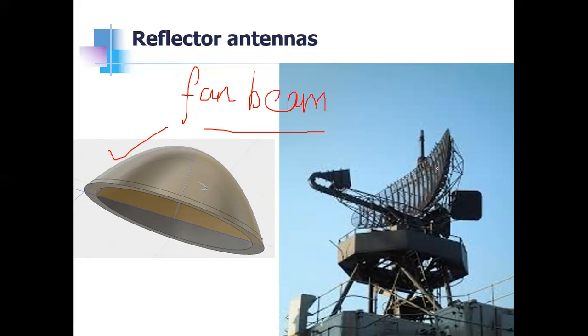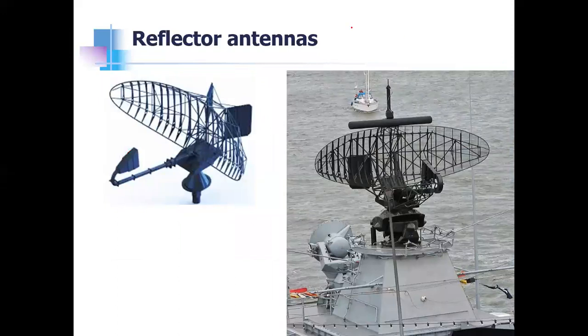What you see here is such a radar, with an elliptical shaped parabolic surface. It has a different curvature in horizontal and vertical planes. The different curvature makes sure that the beams are different in the two planes, that is elevation and azimuth. Sometimes in air surveillance radar, we need the azimuth beam width to be narrower than the elevation beam width. The vertical beam is shaped to provide a broader coverage. The horizontal beam, that is azimuth beam, is made to cover a narrow beam width. For such applications we need this elliptical parabolic surface.